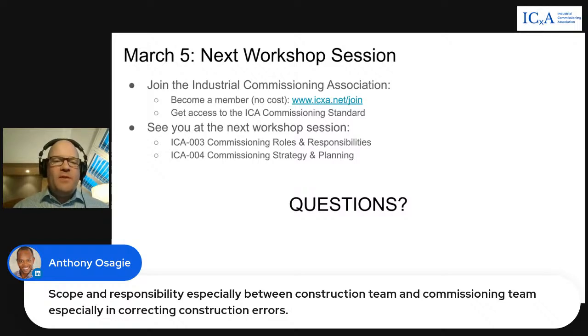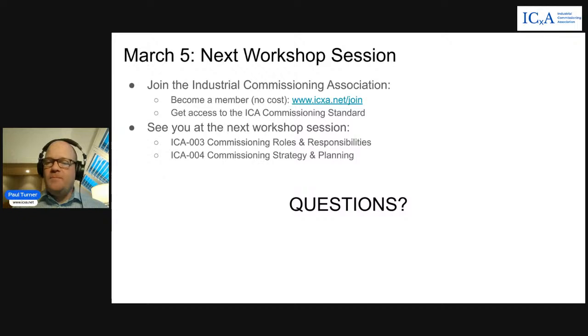They need a full definition of what their work looks like, including their construction completions and systems-based completions. You can't give them that information and expect them to just turn on a dime and make changes to align with the commissioning sequence. That's never going to go well on projects, right? Although that's what a lot of projects try and do. But you need a full definition of all your system completions in contracts so that construction groups have full visibility of what success looks like during commissioning.